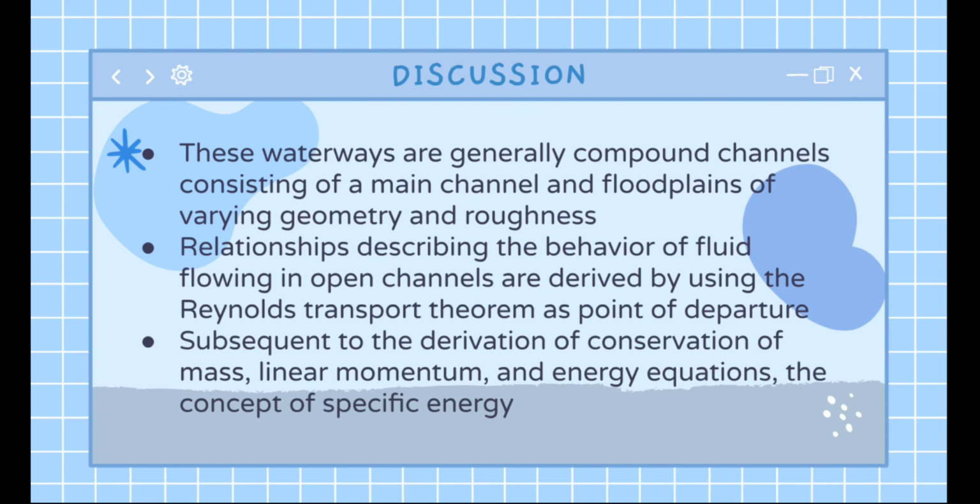The waterways are generally compound channels, consisting of a main channel and floodplains of varying geometry and roughness. Relationships describing the behavior of fluid flowing in open channels are derived by using the Reynolds transport theorem as the point of departure.